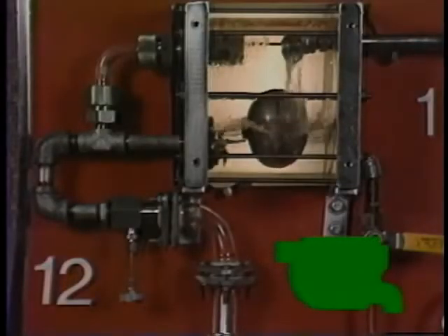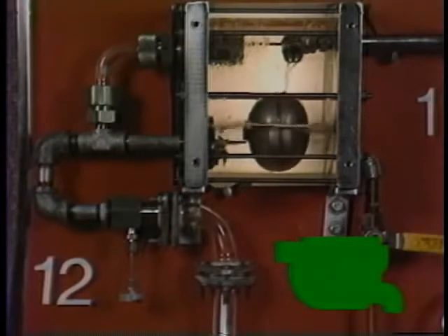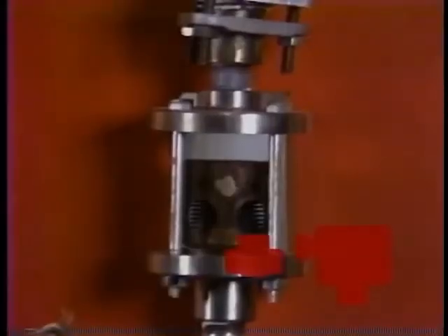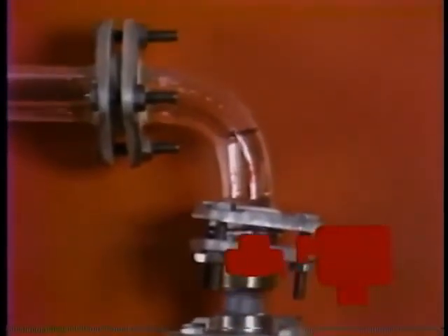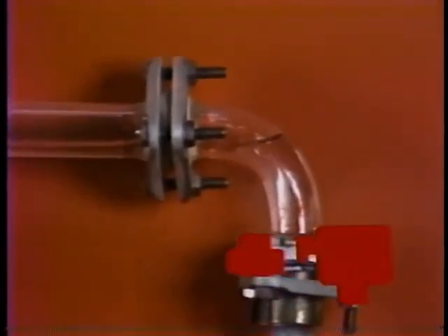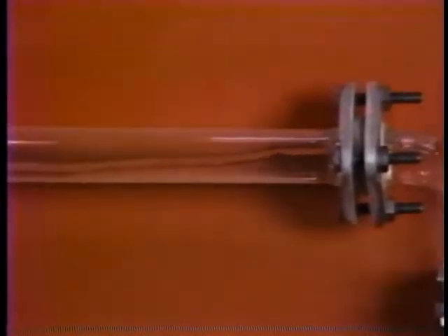The F&T traps air above the condensate seal and vents it through the thermostatic valve mixed with some live steam 15 to 20 degrees below saturation temperature. The disc and bellows traps can both back up condensate. Although this subcools the condensate and air mix, there may be advantages to some systems in using the sensible heat in the water that outweigh the risks of corrosion.